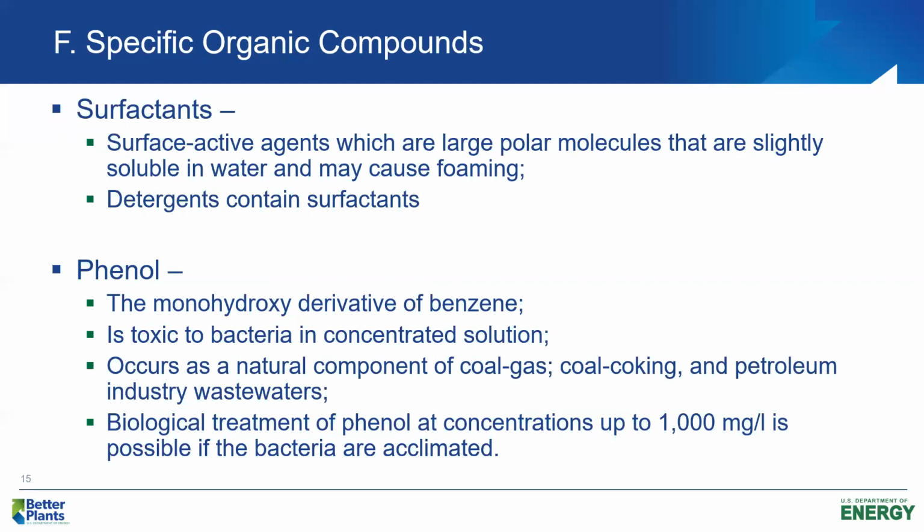In activated sludge, one of the things we try to do is create a great biological flock that's going to have good settling characteristics in the final clarifier. Well, surfactants can deflocculate activated sludge, and that will interfere with settleability and performance of the process. Sometimes certain surfactants can cause the sludge blanket to almost disappear in the secondary clarifier and adversely affect performance of the settling process of activated sludge.